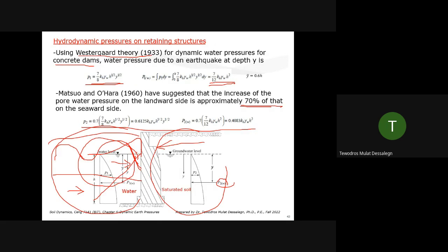During an earthquake, the force on the wall per unit length on the seaward side will be reduced, P1W, and that on the landward side will be increased, P2W. Thus, the total increase of force per unit length of that wall is, so which means during an earthquake, this gets reduced if you credit it. Usually it's taken as 0, but on this side it increases.